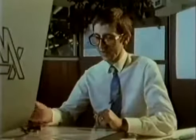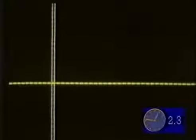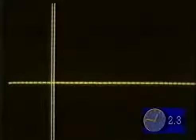CAD supervisor Alan Siswick: All right, well, we'll start off doing this cover drawing in terms of using the system. First of all, we'll set off some construction lines for reference, on a vertical and a horizontal. We can then take some offset lines from there to give us the width. Having put the offset lines in that way, we can come back and put some more horizontal ones in. The offset construction lines will be used to build up the outline of the cover's profile.